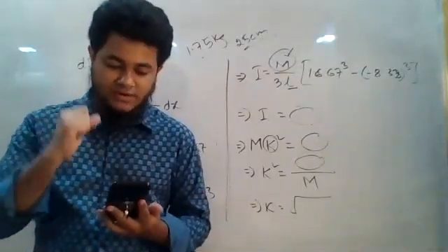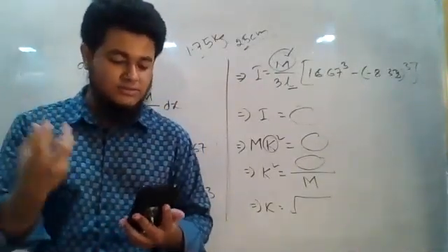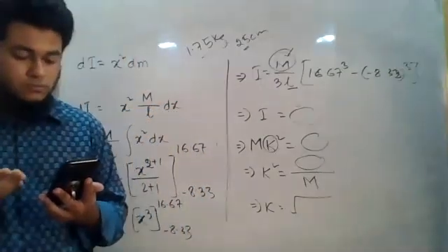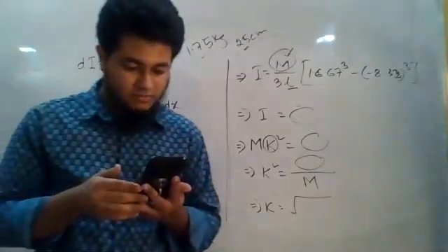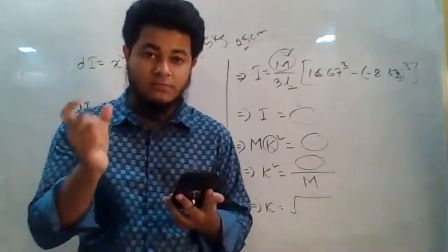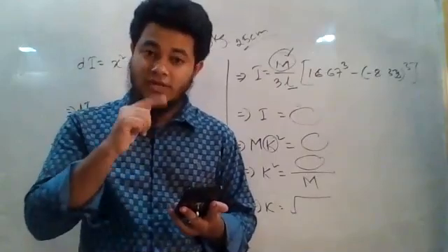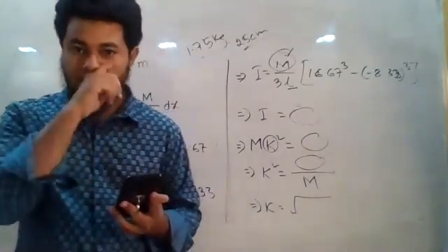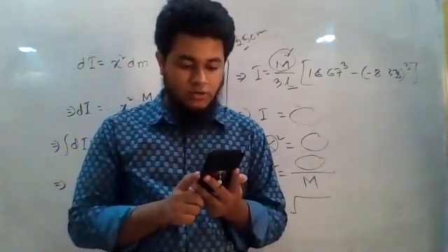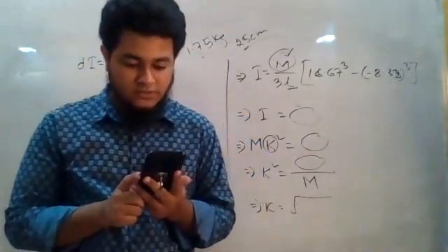So 3 meter is the radius and 10 kg is the mass. Then, 1 meter above from the ground. That sphere completes 20 rotations per minute. Whenever RPM, rotations per minute, is given, you can calculate the angular velocity omega from it by 2 pi n by 60. The rope suddenly tore apart while the sphere was still rotating.